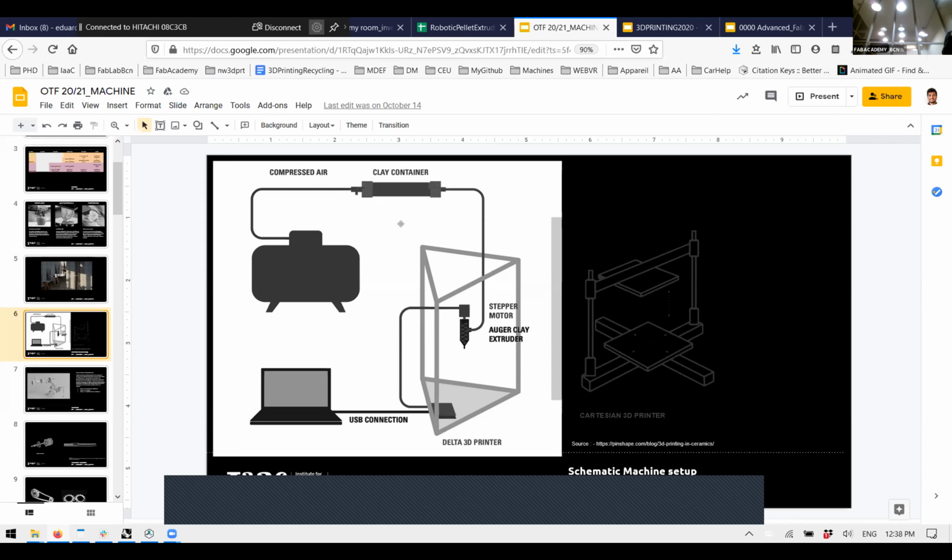And this is something that when we print, we need to account for. When we switch on, it's not immediate. It takes about half a second to acquire pressure and start printing. And when we finish, we release and it still has a little bit of pressure, so we need to wait about 300 milliseconds, more or less. This depends on the consistency of the material. So paste printing in general is easy. Getting good quality paste printing, that is the tricky part.